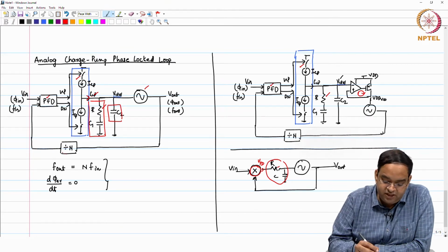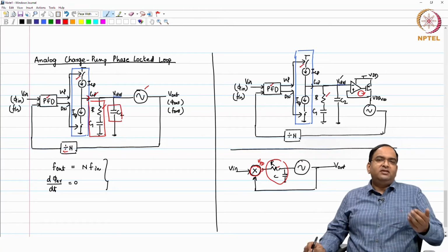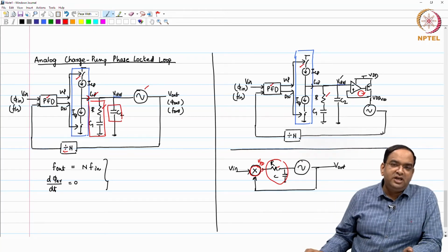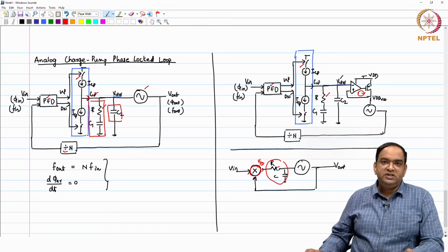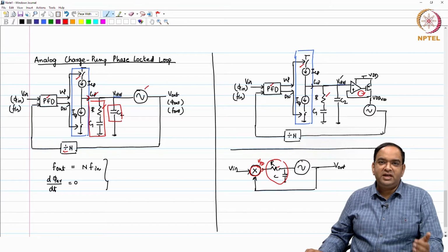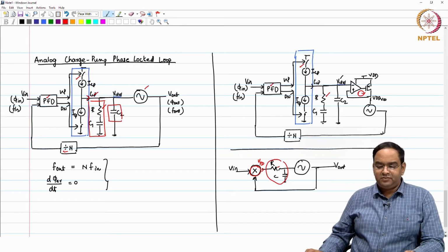Then for the frequency multiplication, we need to have the frequency divider. We looked at a simple divider using D flip flop or TSPC flip flop, where we can easily divide by 2 power n numbers. We also looked that we can get different frequency division by using a cascade of divide by 2 or 3 circuits.